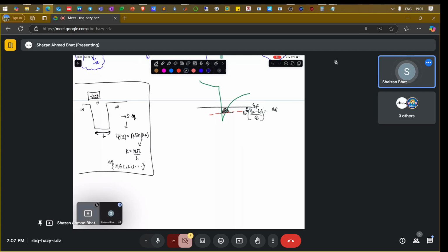So using this particular solution, you get discretized energy levels: n equals 1, n equals 2, n equals 3, and so on. But note that quantum mechanics says that this n equals 1 is not exactly at the bottom of the conduction band. This is basically the conduction band of the well. It's not at the green position.